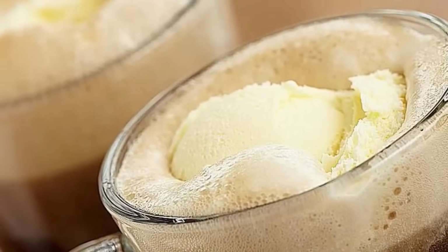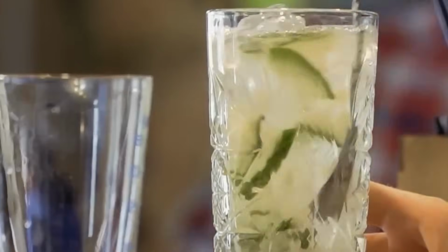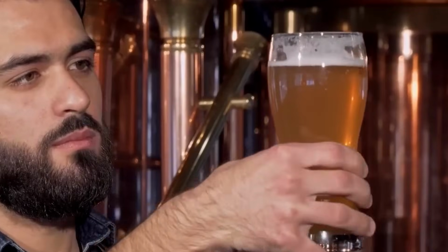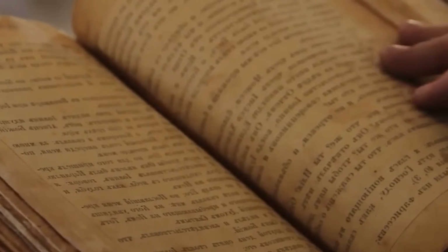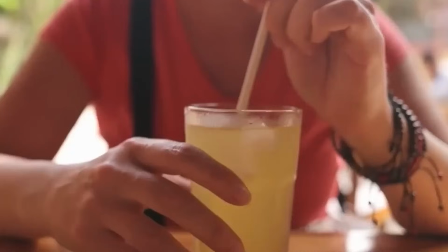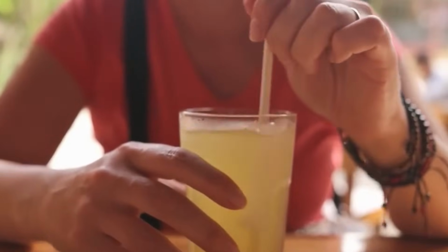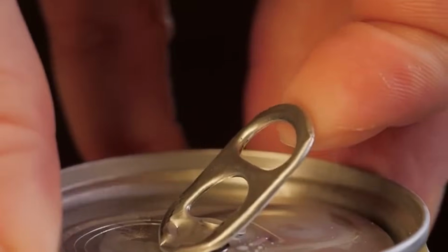After softening, the water is subjected to reverse osmosis using high-pressure pumps to force it through semi-permeable membranes that separate out dissolved solids, bacteria, and unwanted ions. The treated water then undergoes ultraviolet sterilization and sub-micron filtration to achieve microbiological purity before being transferred to agitated, sealed stainless steel storage tanks for use in the product blend.